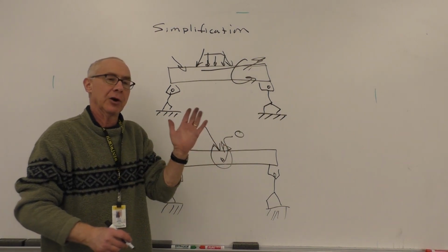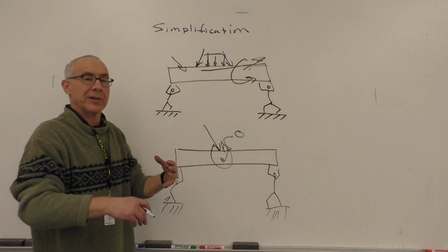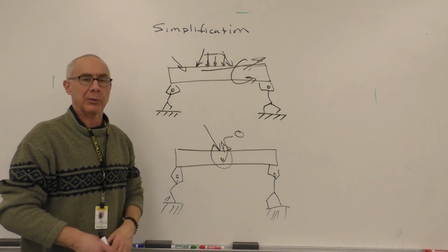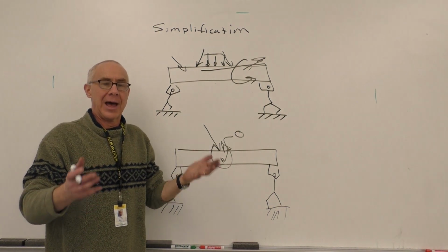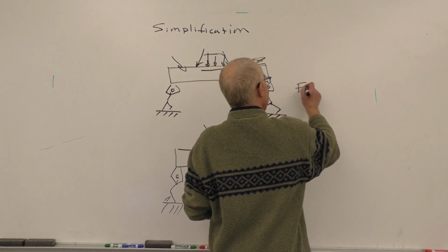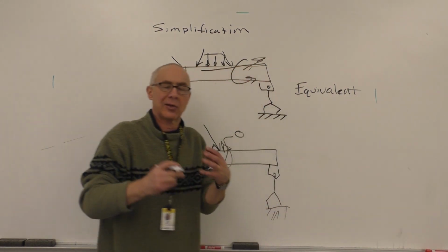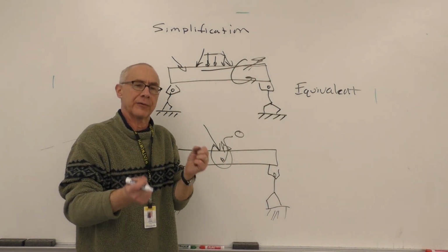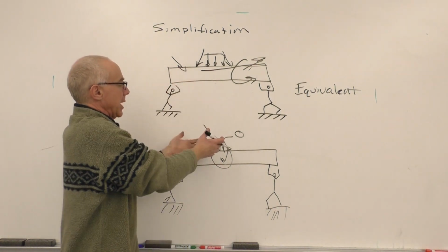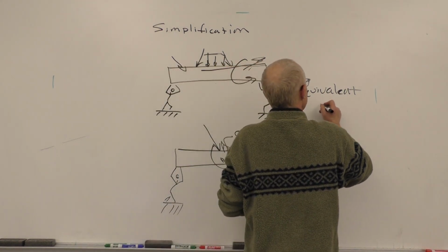These people, they can't look up, right? And if you ask them, is the system of forces different in this case or this case? They would go, we don't know. It feels exactly the same. So that's the sense in which it's equivalent. It's equivalent in the sense that the forces provided by the external supports are going to be identical, although you've reduced it from many forces and moments to just one force and one moment. So equivalent meaning the external